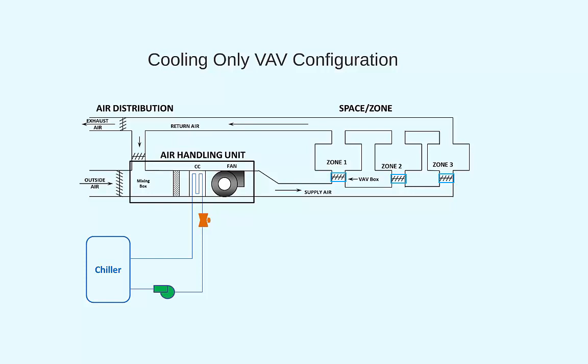First off, back at the air handling unit, we have the chilled water control valve modulate to maintain a constant discharge air temperature coming out of the air handling unit. So that is a closed control loop. The set point for that discharge air temperature should be around 55 degrees Fahrenheit. This temperature will ensure that some dehumidification takes place back at the cooling coil.